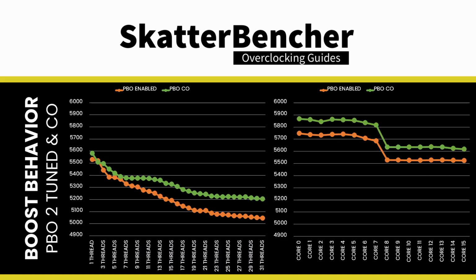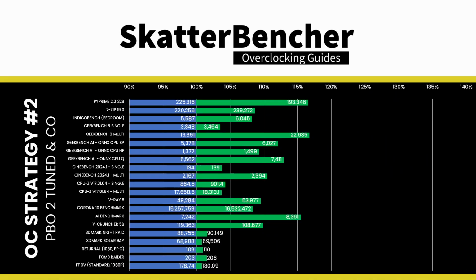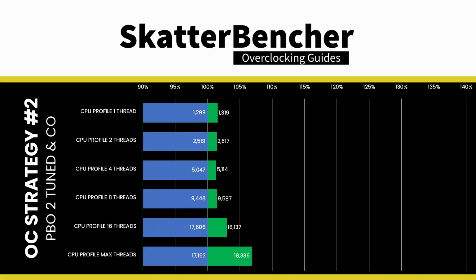In a light single-threaded workload, all cores in CCD0 can boost to over 5.8 GHz, and all cores in CCD1 boost to over 5.6 GHz. We reran the benchmarks and checked the performance increase compared to the default operation. By adjusting the Fmax boost override, scalar, and curve optimizer, we both undervolt and overclock both CCDs of this Ryzen